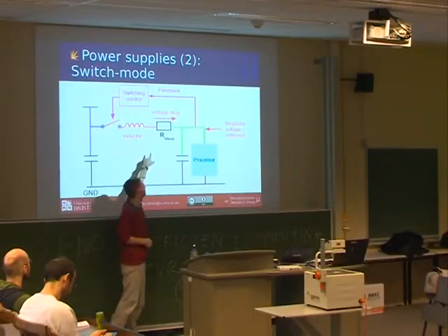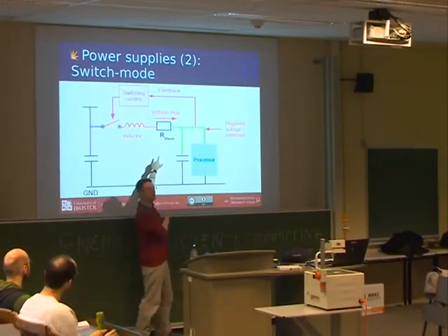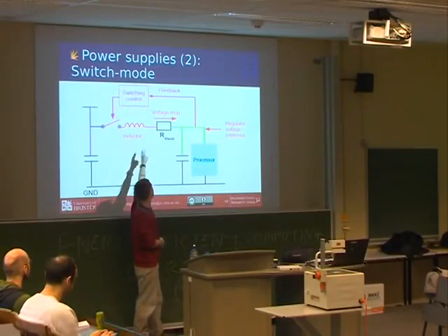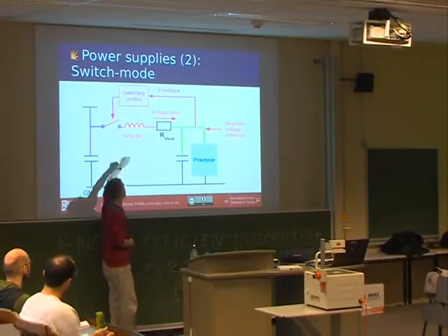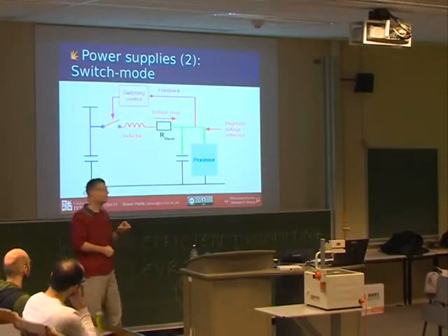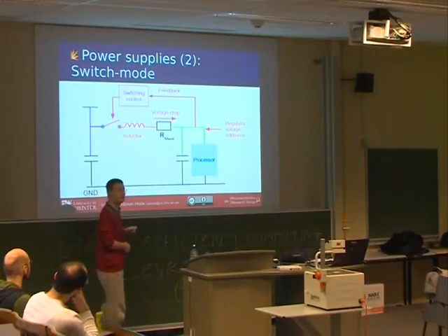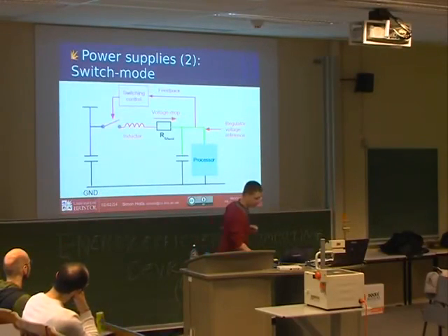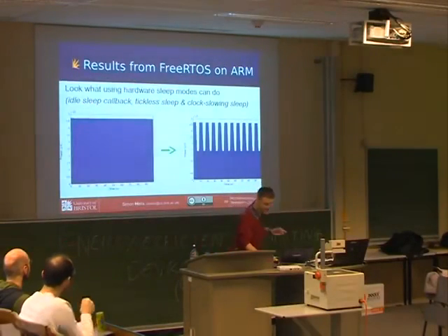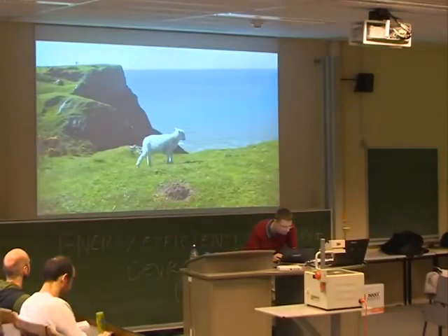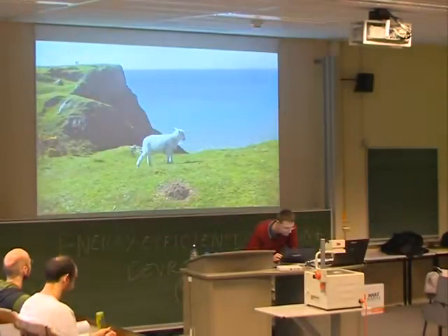So you've got the shunt resistor in. As long as you put the shunt resistor before the feedback, and it can be in either order with the inductor and in either order with the switch, then you will get feedback that ensures that the voltage across there is adjusted for automatically. So what that would look like in the same example is 5 volts goes in. Oh gosh, my end button and my page down button are the same.